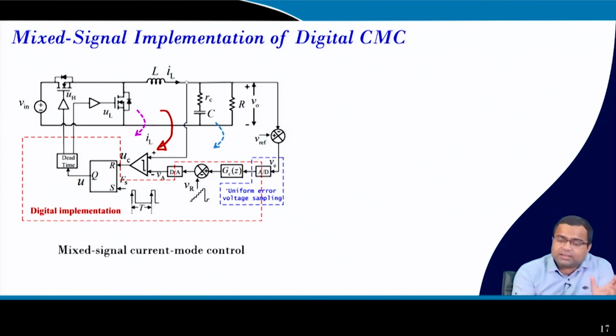What is the advantage? Since you have a compensator in the voltage loop, you can play with the tuning that you have learned, right? We have already talked about gain scheduling and different types of control algorithms, where you need to adjust the controller gain based on the operating point requirement. We have also learned large signal tuning, where we need to update the gain based on the operating condition. So, that can be easily done in the digital controller.